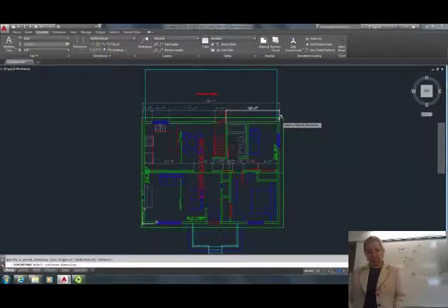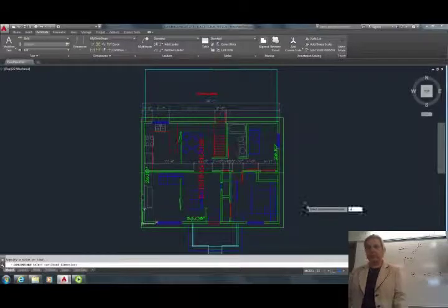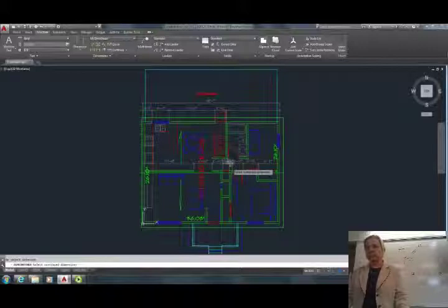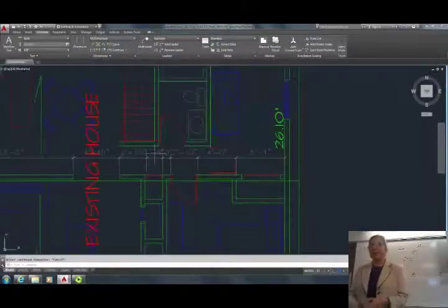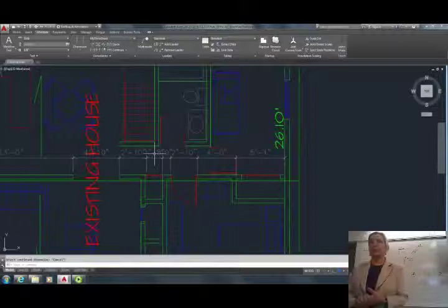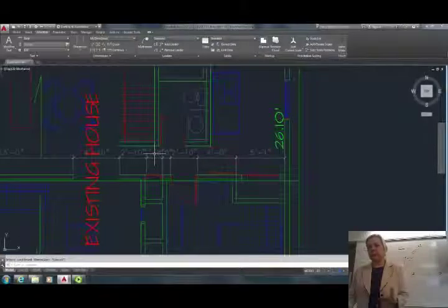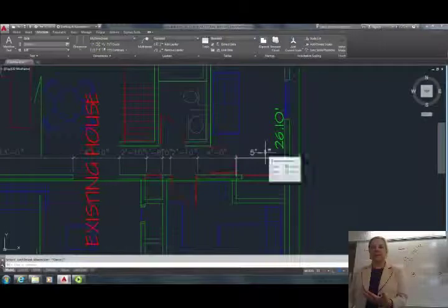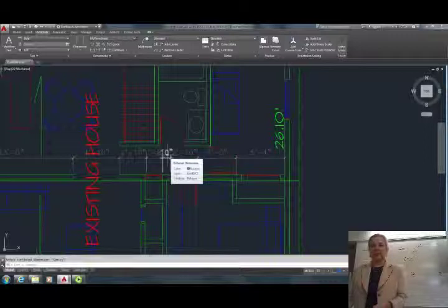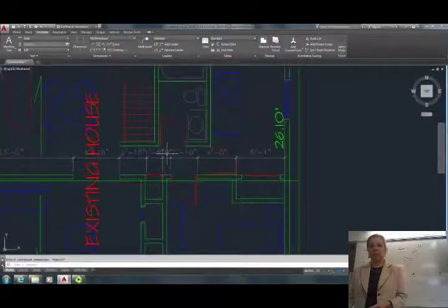But I want to concentrate on something more important. Your drawings, as generated by computer, may not come out very clear here. Okay? So here is where, before you finalize your final project, you should look at your dimensions, say this is clean, I'm a little bit too congested here. Now you can either remove that dimension at all, place it somewhere else in another string, or take this dimension, grab the text and move it. So you see this one is showing as 10 inches below.